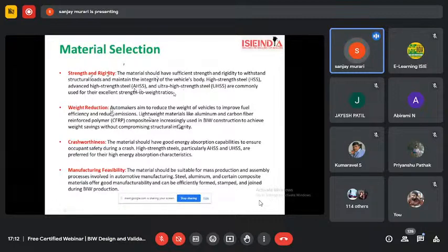So though the aluminum may provide good efficiency, the cost will increase. Next comes one more material which is much better than the aluminum. That is nothing but again magnesium. But magnesium cost and availability wise, magnesium is less available, and the cost of the magnesium is also too high. But strength wise, again magnesium has some good yield strength.